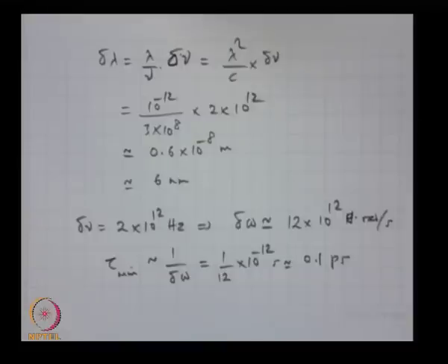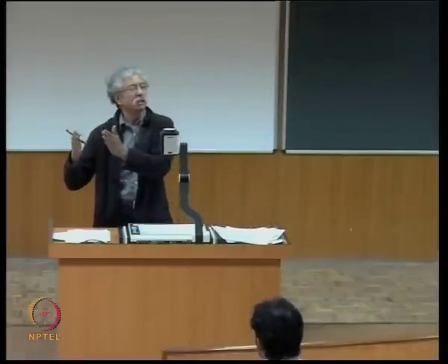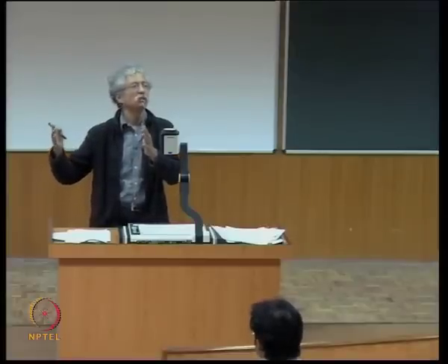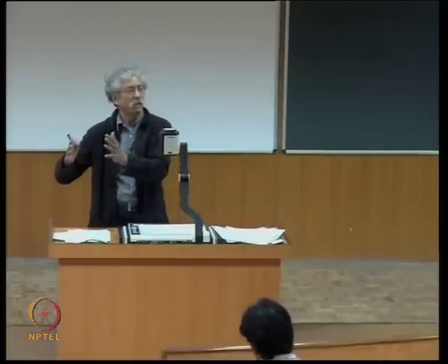Okay, so what is actually happening is, I start with a 1 picosecond pulse, propagate through this medium, it remains 1 picosecond approximately, but its spectral width increases because of this self-phase modulation. Because of the nonlinear effect, the 1 picosecond pulse which was launched has increased its spectral width. Delta omega at the output is more than delta omega at the input.